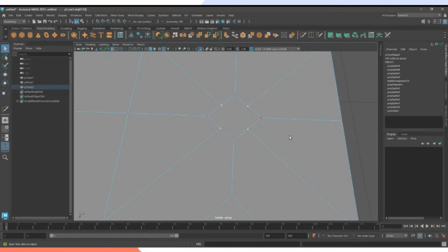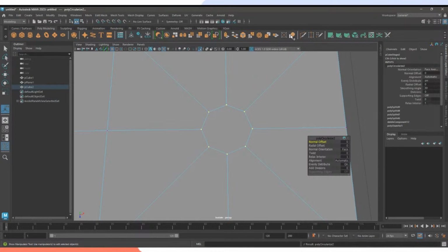One of the ways you can make a circle is either to do it manually by using the resize tool, the scale tool, and then boom, you have a circle. But sometimes it's not going to be a perfect circle. We want a perfect circle. So we're going to undo that. Select the rest of our vertices. Press Q to go back to selection tool so you don't mess around with your selection. And pick the circleize tool. This is a tool that you can use. You can either use manual or tools. Tools are cool. Boom. A perfect circle.